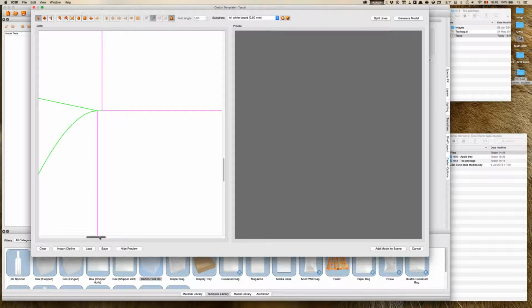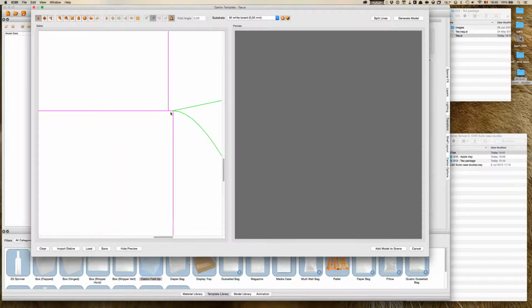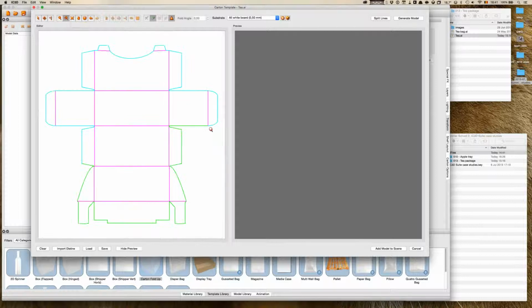If you want to know more about that, I actually did that webinar about the iC3D version 3.03, and in that one I explained some carton fold mysteries, and actually this was one of the example files that I used. These need to be cut lines, and if you don't make them a cut line, then it is not going to work correctly.